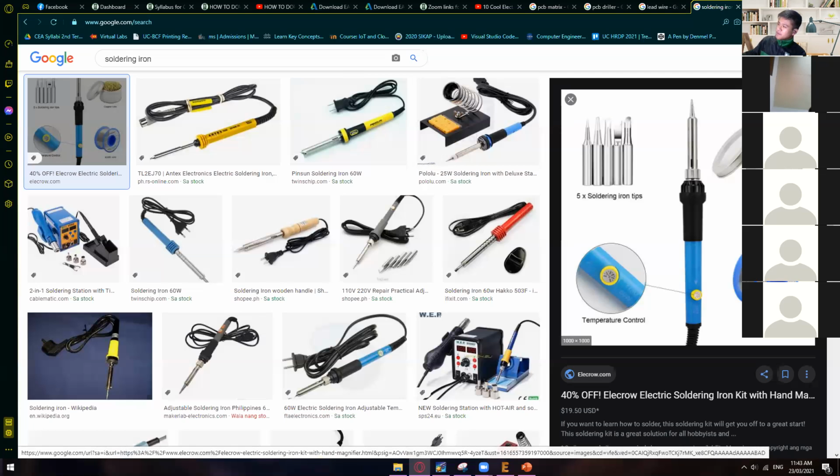Okay. So the role of this copper wire is you should always wipe it while you're using your soldering iron and lead, right? So you should always wipe it with your copper wire. Do not let the lead stick on your soldering iron, especially on the tip, because it will melt or burn the tip of your soldering iron easily.